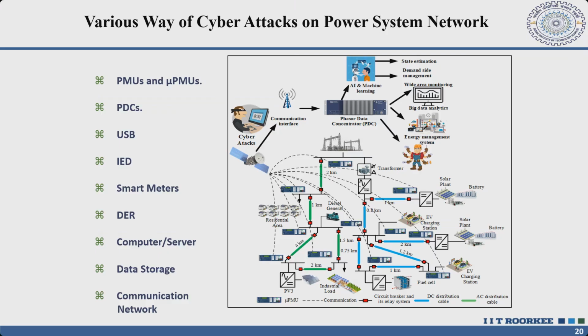They call it contract demand. Let's say if one company is there, for example, our IIT Roorkee, we have a contract demand of 1 megawatt, right? So for 1 megawatt, per kVA, whatever amount is fixed by IIT Roorkee and the utility, UPCL in our case, Uttarakhand Power Corporation Limited. So that amount is fixed, let's say per kVA 5 rupees or 10 rupees, multiplied by 1 megawatt converted into kVA. So that much amount you have to pay every month, right?